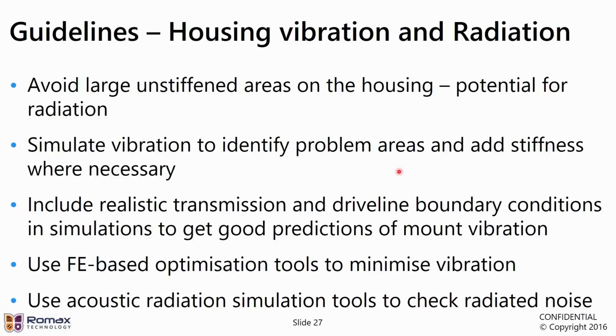Now, it depends on what you're trying to model. If you're trying to model a test rig, for example, then the mounting conditions and the boundary conditions will be different from if you're trying to model a more realistic scenario of the gearbox and driveline in operation. But whatever it is, we want to make sure we're modeling what we're testing and testing what we're modeling.